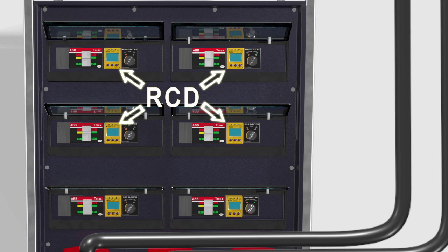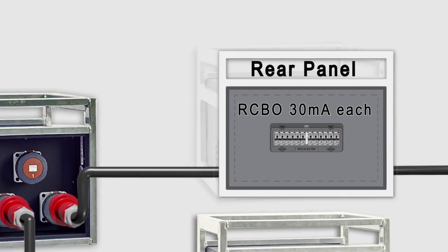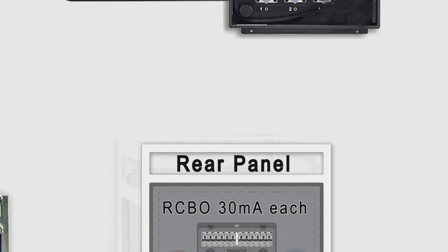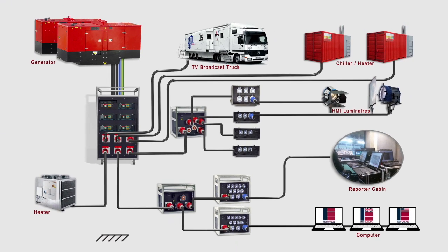They also provide increased fire and system protection. They work by detecting residual current flowing to ground, for example, caused by an insulation fault, and switching off the defective circuit before it can present a risk to people.